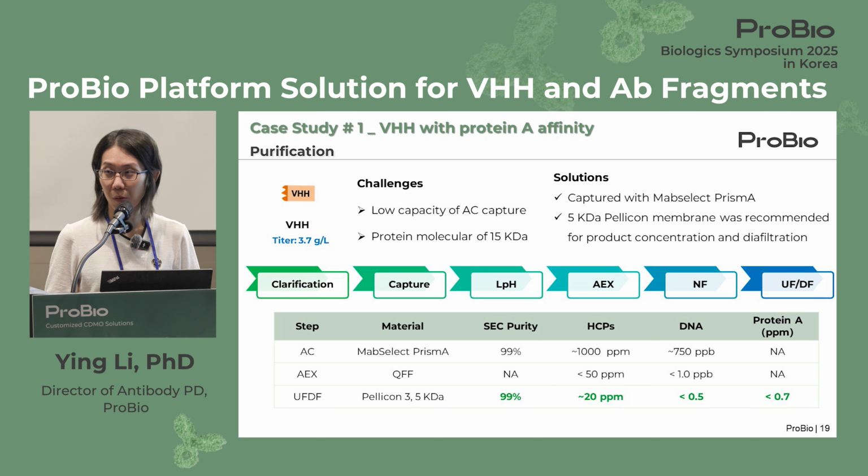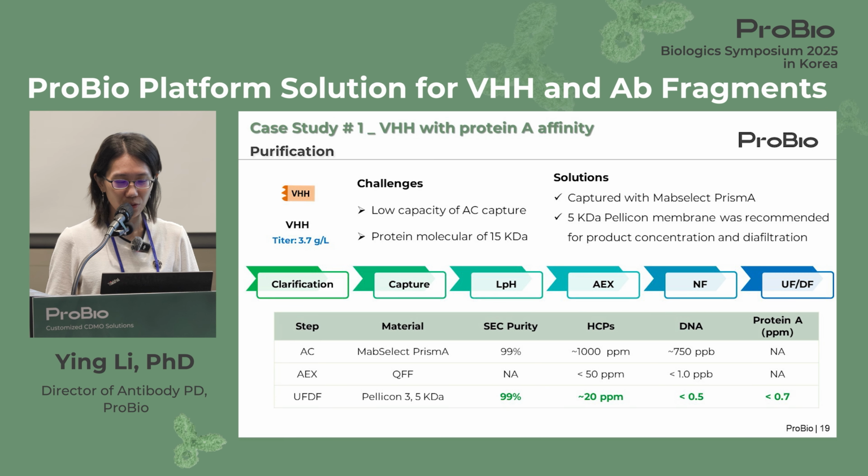And in our platform, we have done a number of cases with just 2-step chromatography to successfully reduce the residual HCP level down to within 100 ppm and with SEC purity greater than 99%. And just bear in mind, because of the small molecular weight, we have to utilize a small molecular weight cutoff ultrafiltration membrane for the UF-DF buffer exchange process.